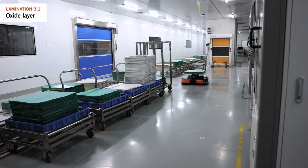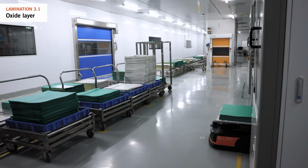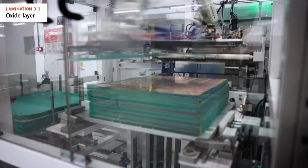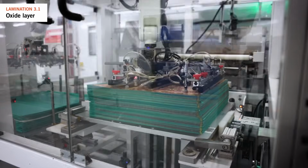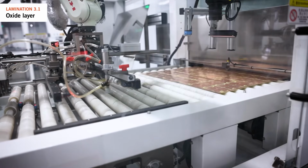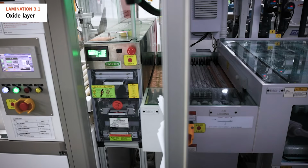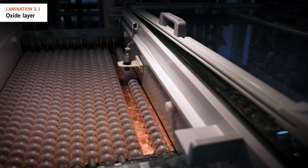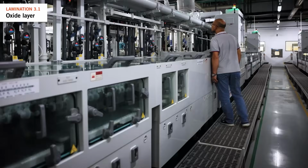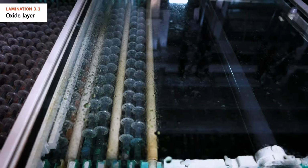In this process step, the inner layer cores are prepared for bonding. Later, during lamination, they will be bonded together using prepreg sheets as glue and insulation between the conductive layers on the inner layer cores. The oxide layer is necessary to prevent copper from corroding and helps the copper stick well to the resin in the prepreg. We clean and slightly roughen the inner layer cores through a simple process of cleaning and micro-etching. Then we apply an oxide layer.